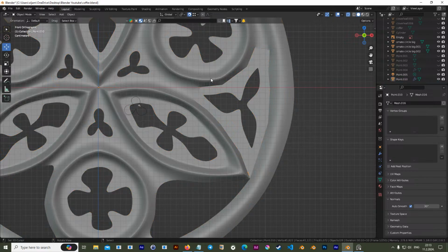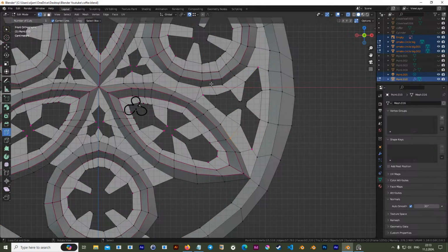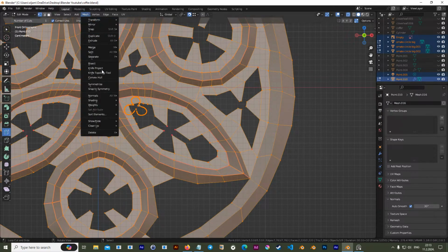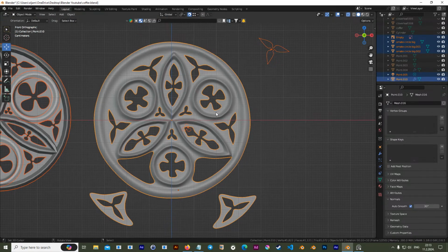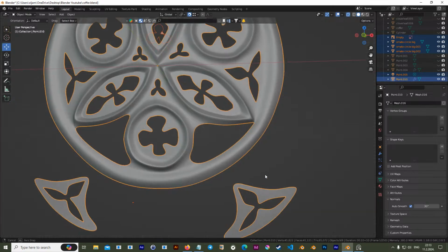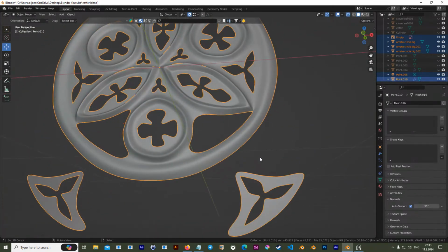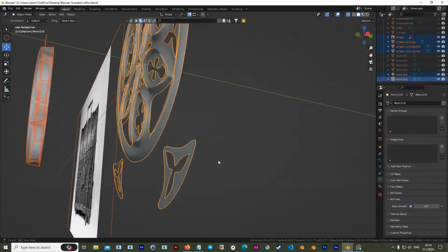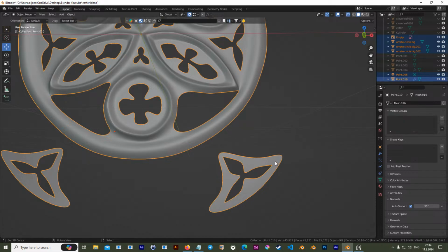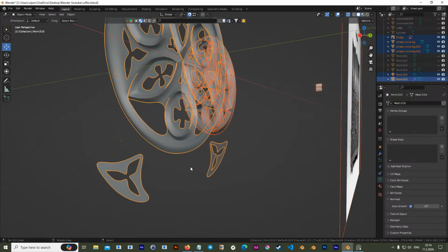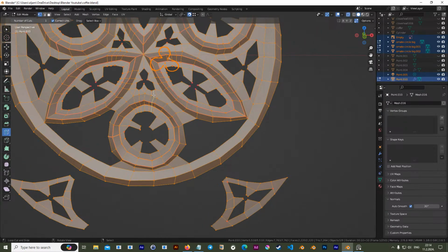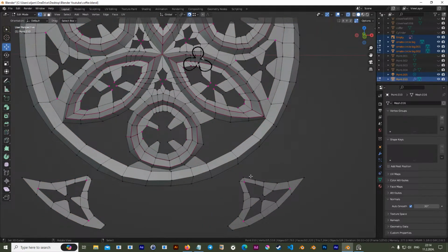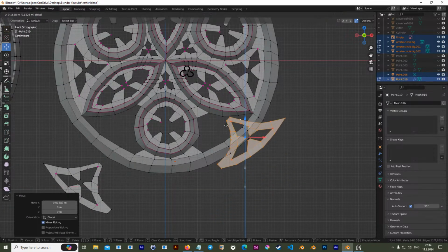In case you're wondering why this looks different, the mesh normals are not facing outside, because I rotated. When you draw something, normals are looking at you. If you rotate it and merge it with another mesh that is not rotated, the normals will be on the other side.